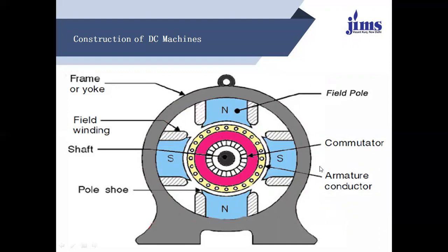Some machines are two-pole machines, so over there is one N and one S. There is a commutator. In between of that you are finding that there is a shaft. Shaft will be simply a rod which holds the entire rotor part of the machine. Then there are commutator segments. Each black part indicates an insulation, and that insulation will be mica insulation. Whatever white we are looking at over this side, that white part is the commutator segments.